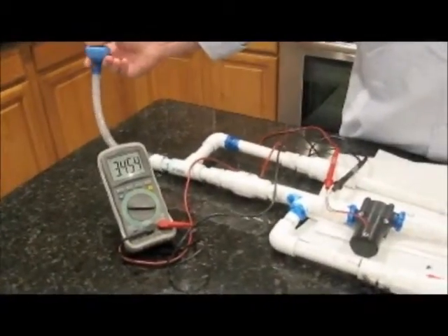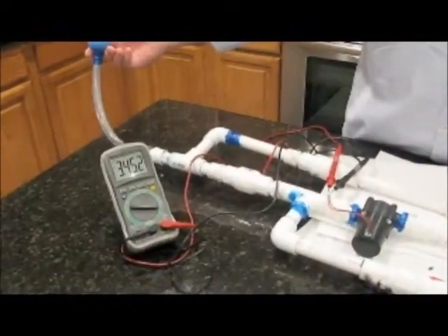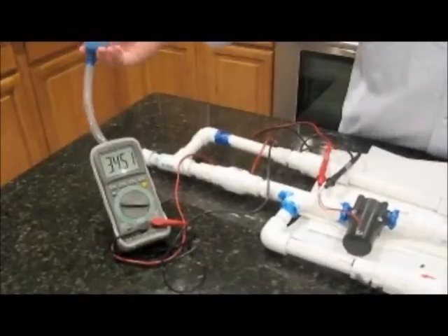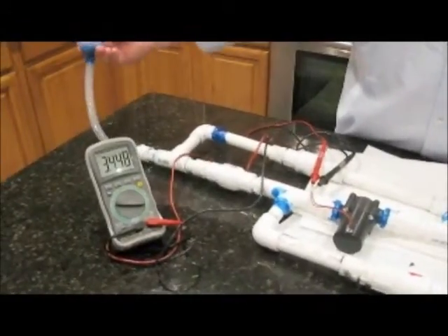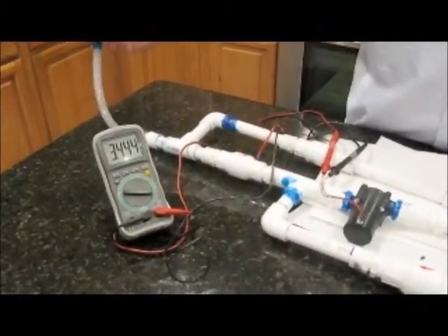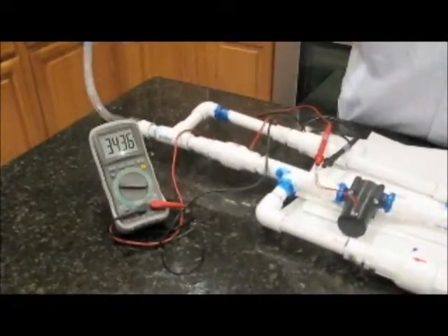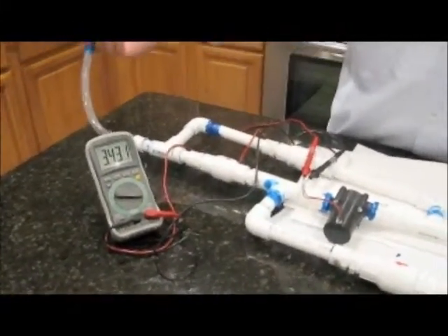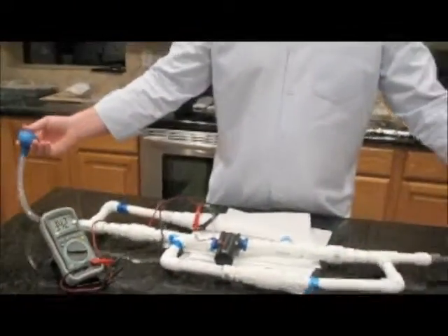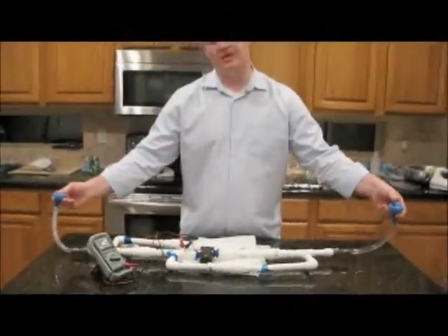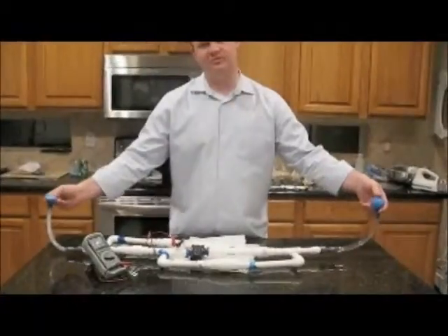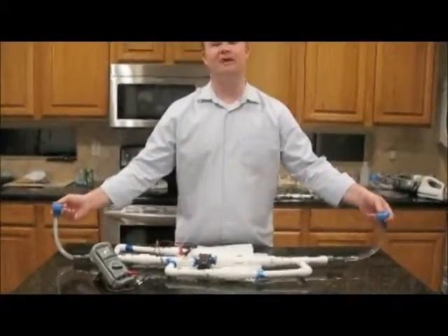As you can see, it's normalizing out to about 3.4 to 3.5 volts. And this setup was designed to steady out at about that exact range per the datasheet. With this information showing that that's what's being measured, we can take this now, and the other half of the prototype will be simulated on a breadboard with the electronics that will allow that voltage to then be regulated for use in a USB connection.